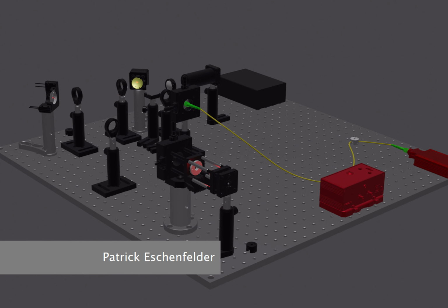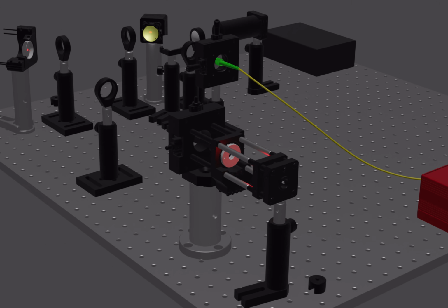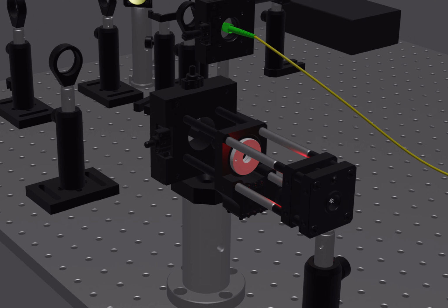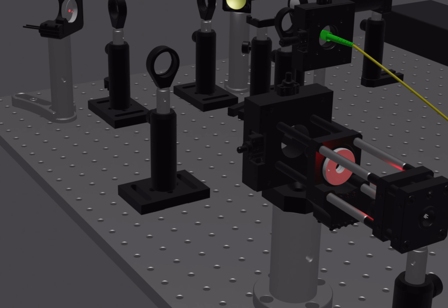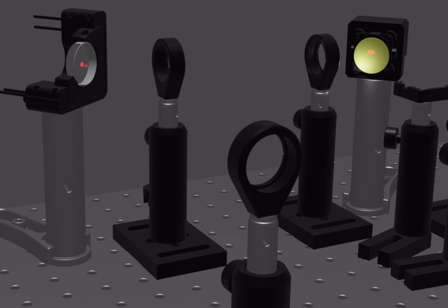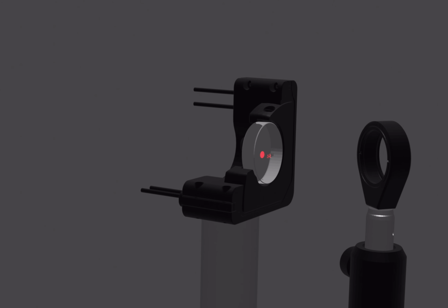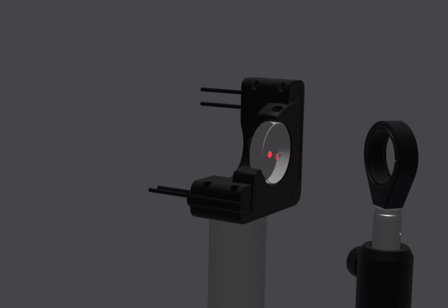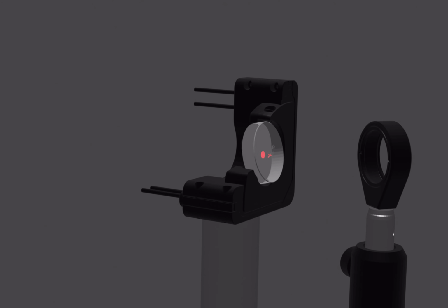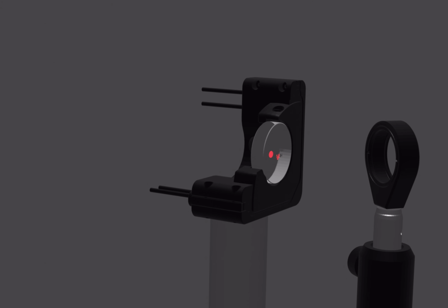The Laser Communications Fine Tracker consists of two subsystems, the error emulator and laser fine tracking systems. Starting with the error emulator, we see the laser system, which is housed in a cage to aid with alignment. The beam from the laser is then passed through a collimating lens to collimate the light, which keeps the beam from diverging as it passes through the system. The beam then reaches the error emulator mirror, which imparts angular deviation to the beam path. This simulates the effects that would be experienced due to atmospheric conditions on the path from a satellite to a ground receiver, as well as the mechanical variations imparted by the telescope that is intercepting the beam.